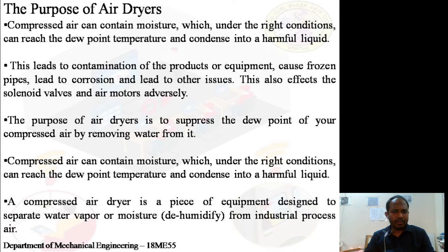Basically these valve ports will be very minute and small, maybe 1 or 2 or 4 mm in diameter, a maximum of 2 or 3 mm. If small particles occupy that space, it will definitely block the valve passages. It may be at the entry or at the exit, but certainly these valves, as I have already told you, are called the brain of the pneumatic systems. If these are blocked, then the pneumatic system doesn't work.